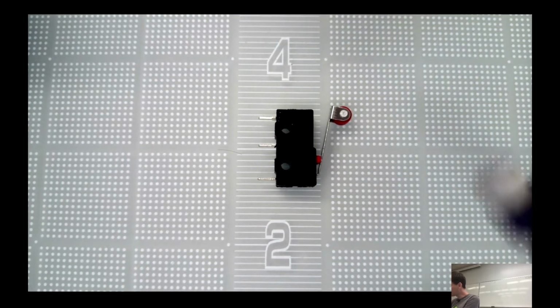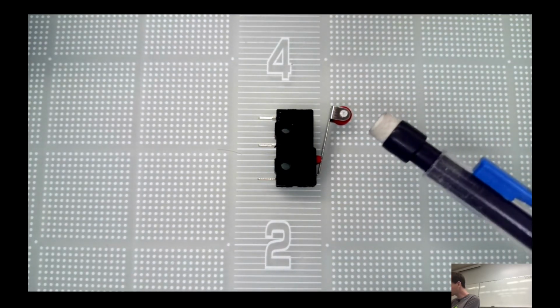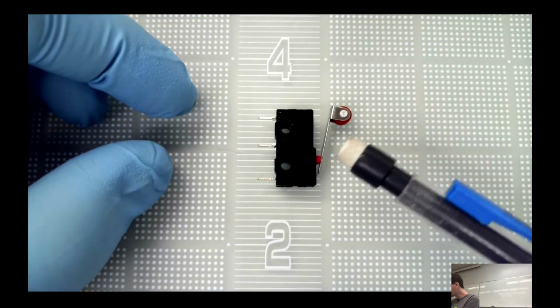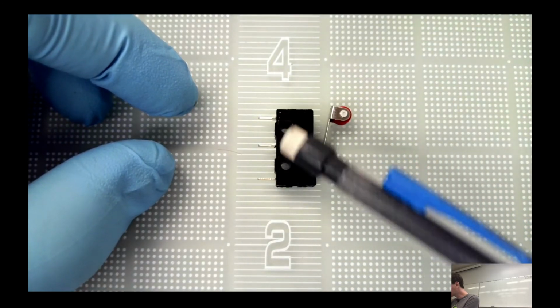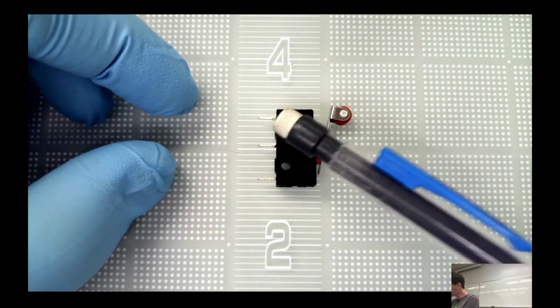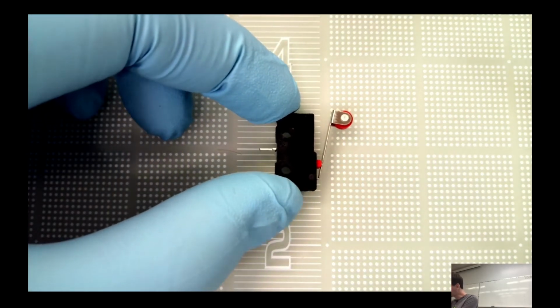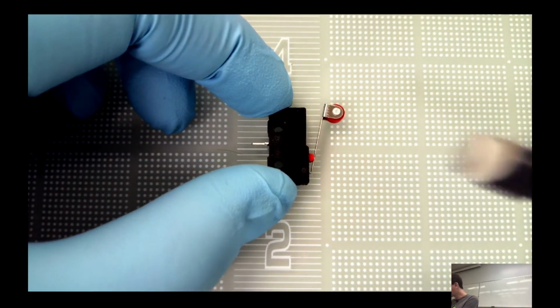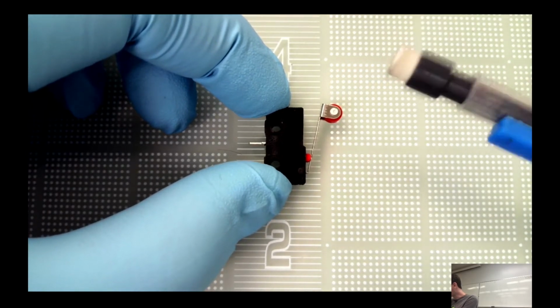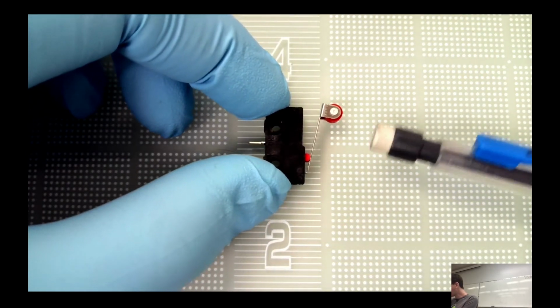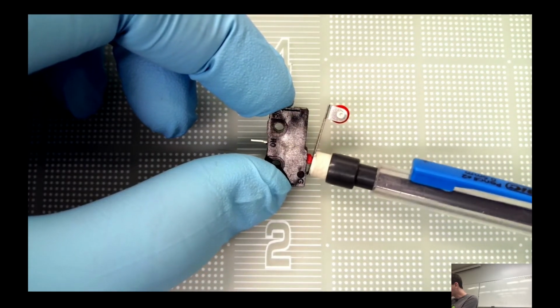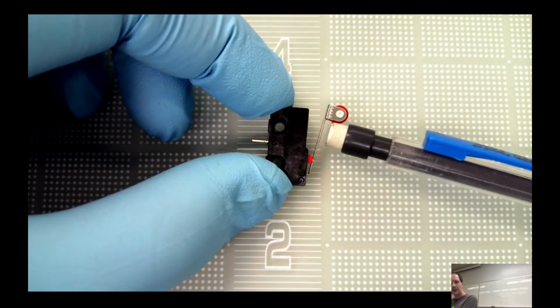This one here is not technically a push button. It's called a micro switch. It has 3 pins. One is normally open, one is normally closed, and then when you push the button, it basically does the reverse, or it closes the normally open one and vice versa. And so the actual little push button is just that little red bit right there.